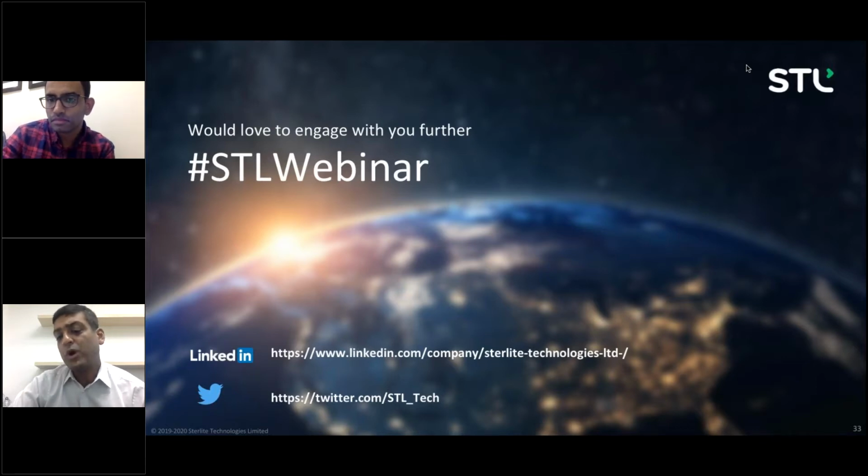MFD is just one of many criteria that you have to use when you're looking at transmission. There are a number of other parameters, and this has actually been the reason why there are multiple different ITU classifications of fiber. In the context that we have been talking about, MFD is critical in terms of making sure that your installation is right. It is one of the parameters that affects transmission, but it's not the only one.